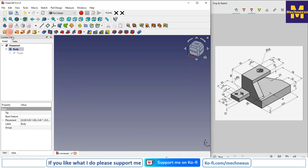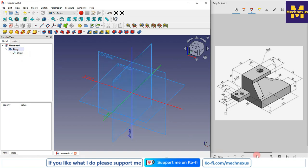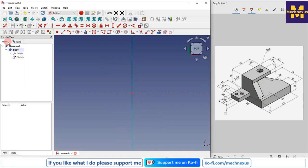And I create a body and I will select my origin plane. So now the first thing we will do is to create this bottom profile. For this we will select this XY plane, which is the top plane, and click on the sketch.